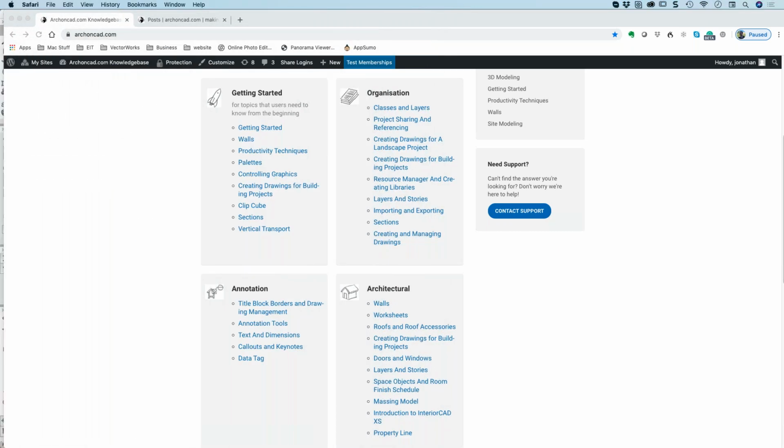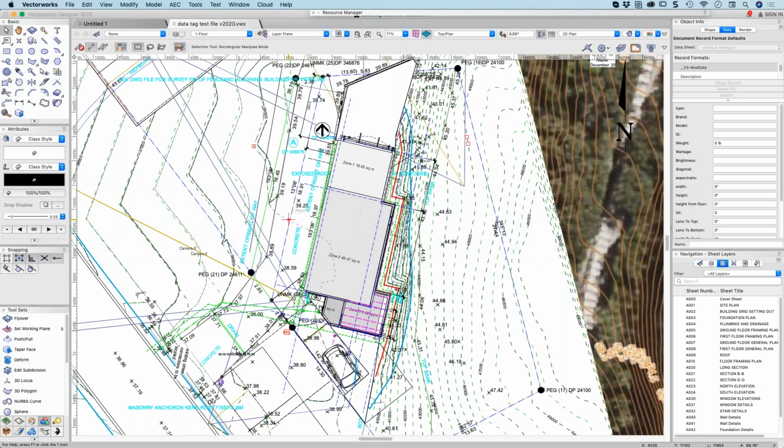I'm just going to put that onto the other screen, and I'm going to go back to Vectorworks. So I'm going to start with looking at saved views. Now, I hope everybody uses layers and classes. They work together. Layers are where things are, and classes are what things are. So, for example, if it's a toilet and it's on the second floor of the building, second floor is the layer that it is in, and the toilet is the type of object.